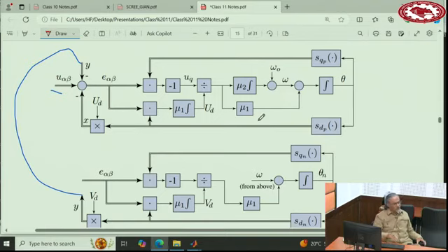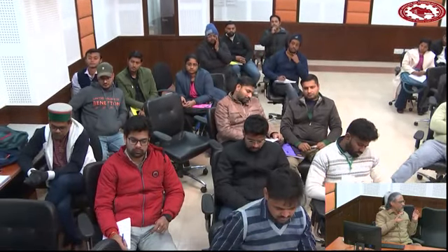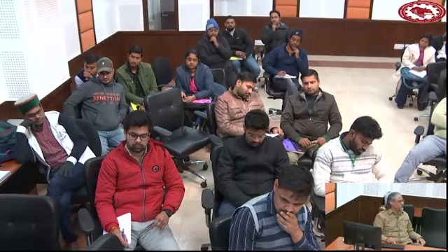But my experience, I'm going to tell you, is that if you do a good, correct simulation in continuous time, compared to digital time, the only thing that you are missing is that one sample delay. And then you can always go back to your simulation and, after your continuous time controller, put one sample transport delay. So this is, I would say, chiefly equivalent to a digital control. If your simulation runs with one sample delay, 1.5 sample delay, in continuous time with no problem, it will run in digital without problem.